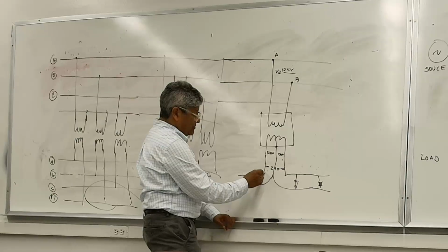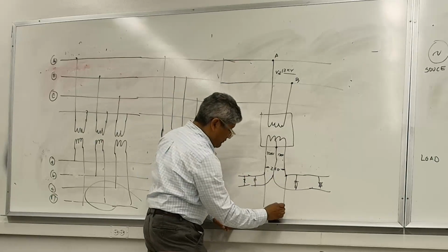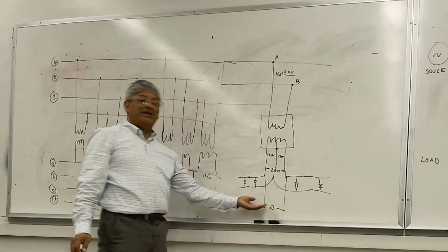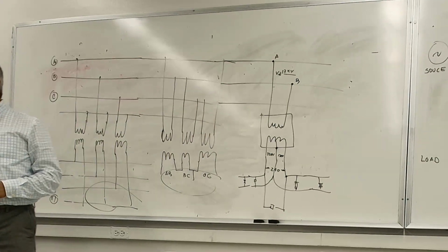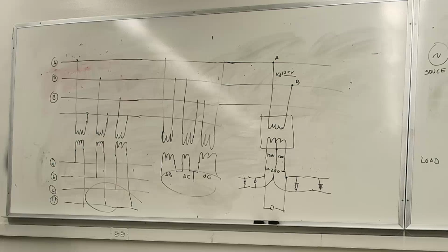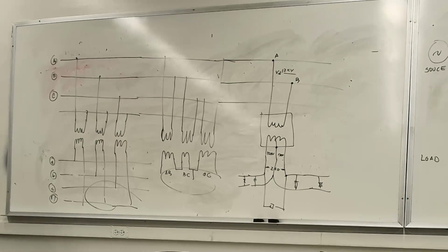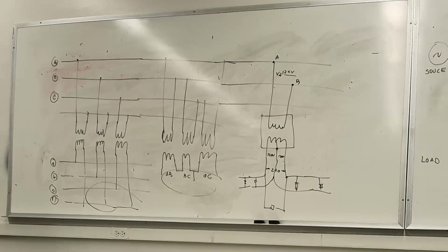Or you can actually say, oh no, I have a 240 volt load right here. In some cases you need 240 volts. A typical 240 load is your washer, and you've seen the plug on the washer, right? Or your dryer. It doesn't look like a 120 volt plug, right? It looks like a prong. So that's most likely a 240.